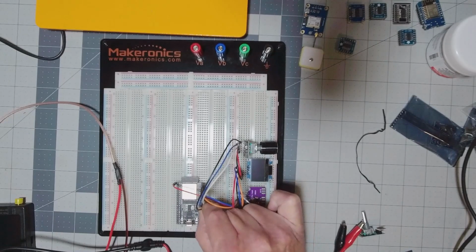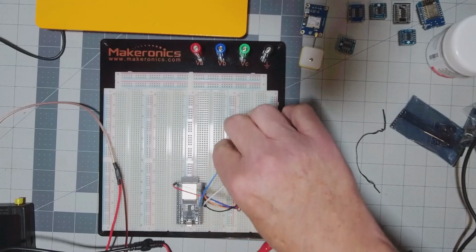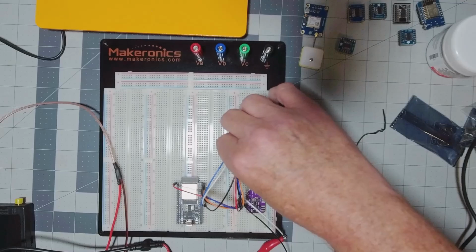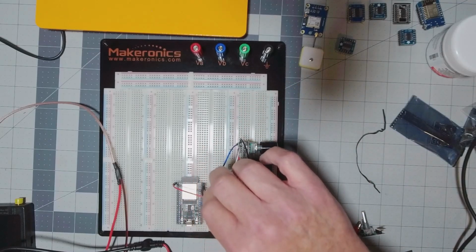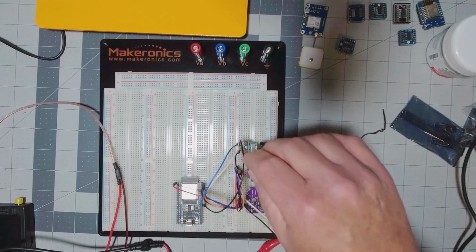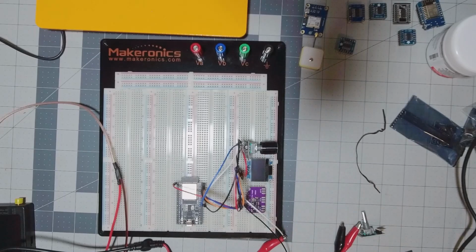The blue line coming off of this is GPIO 18, going to the data line, which is the 4th pin. And 19 is going to the clock. Then I just piggybacked the power and the ground off of our existing connections from the OLED display.